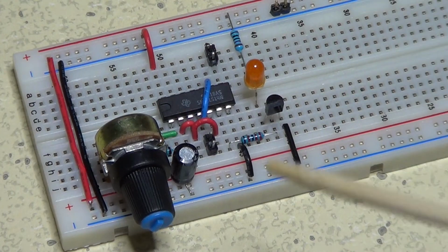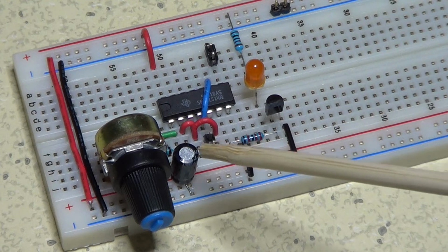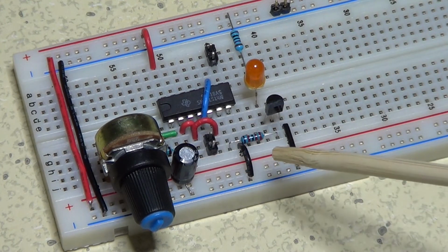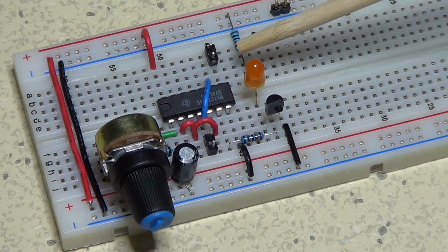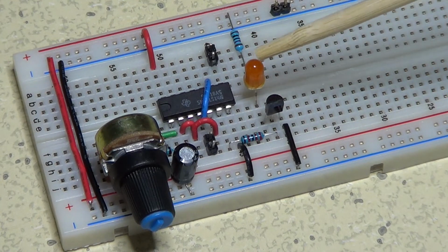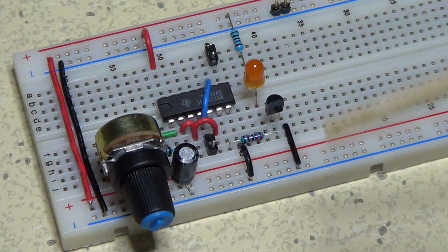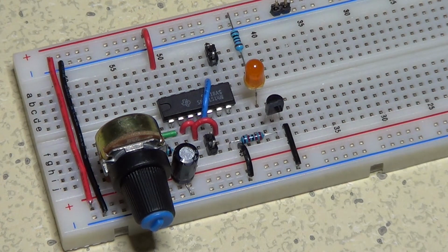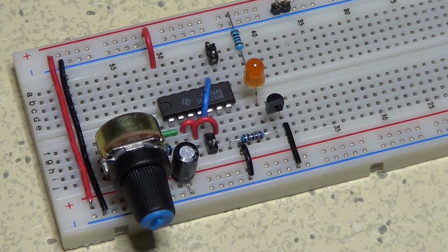And this one is the capacitor connected to the input of the first Schmitt trigger inverter in the IC. This is the resistor on the base of the transistor, and this other one is the resistor that limits the current through the LED. I also added some test points to be able to connect the oscilloscope, so we will be able to see the actual signals emitted by this device. So, let me power up the circuit now and connect the probes, and let's look at the output signals with the help of the oscilloscope.